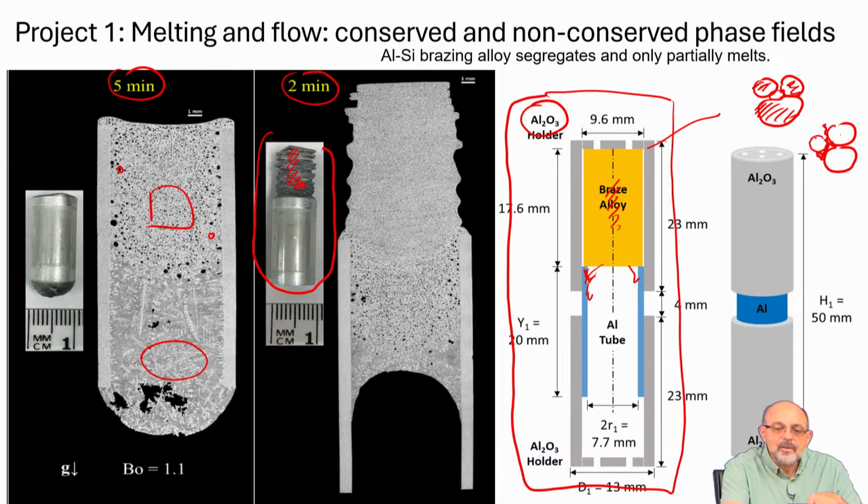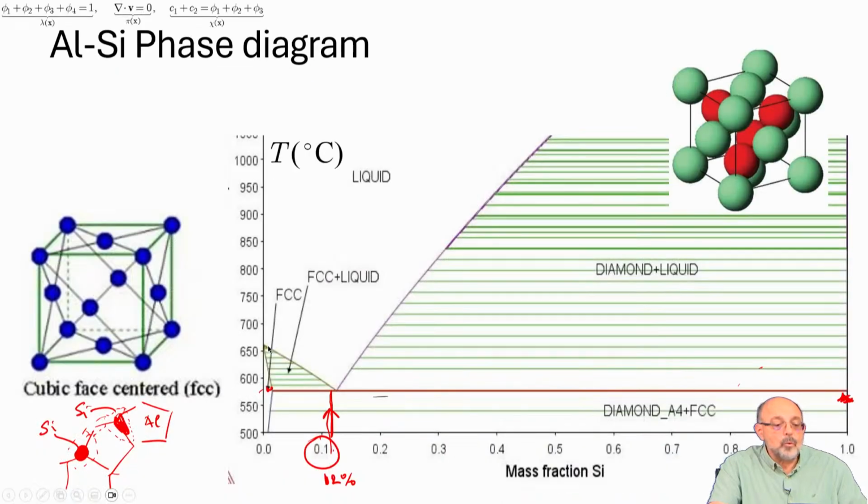These are white grains, and black, very black holes. These are voids, right, and they're spherical. Here you see the typical eutectic solidification with dendrites. So we are solidifying from near eutectic composition, dendrites and everything that you see in traditional metallurgy. So that's qualitatively what happens.